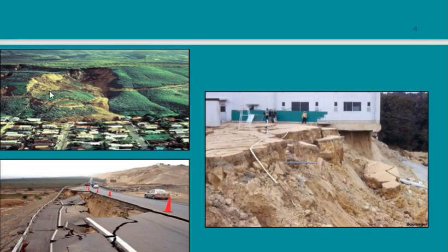In this case of loading, is it a finite failure or an infinite failure? What do I mean by finite or infinite? Finite means the failure is local. I have a local failure in an area. Infinite failure means a whole stretch is going to fall, because all of this is my slope. But the failure happened from here to there only. So this is a finite failure.